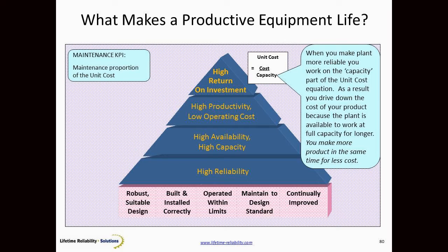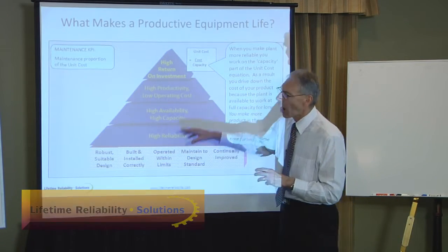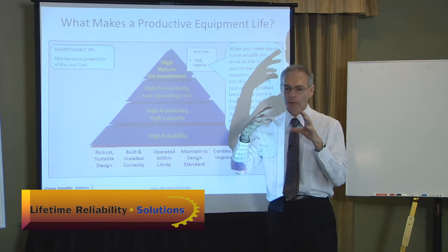Now, reliability, we know, depends on foundational concepts as well. The initial design choice is vital. If we get the wrong design choice, you put a racing car out in a paddock full of rocks, that racing car isn't going to make it. It has to be installed correctly with very low stress. Things aligned correctly, the installation with round shafts, properly clearanced bearings and other parts of machines. Got to operate it within the design envelope. Got to maintain it to the design requirements of the manufacturer, because they have got a limited scope to run